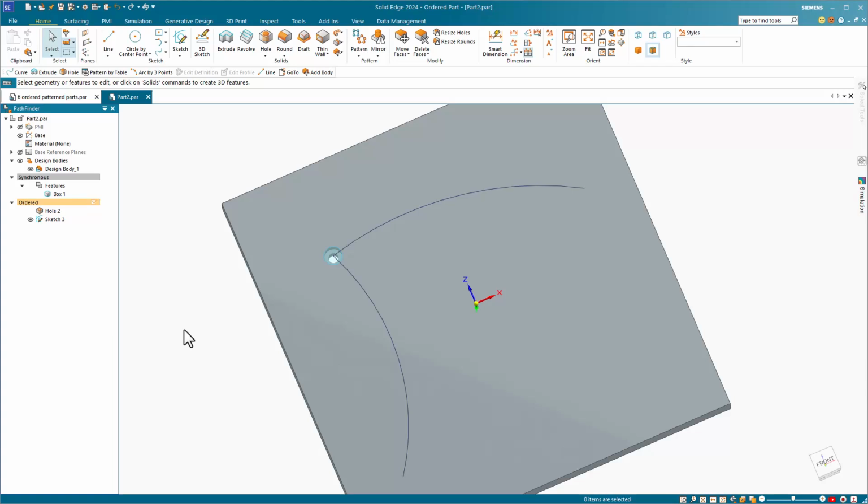In Solid Edge, this is a little bit different from other types of features. Other features allow you to draw a sketch that you need for the feature while you're creating the feature, but the along curve pattern requires you to create the sketch ahead of time. So that's what I've done here. I've created a sketch with 2 arcs. These could be arcs or splines or straight lines. You could also use edges and other entities. So let's get started looking at this feature.